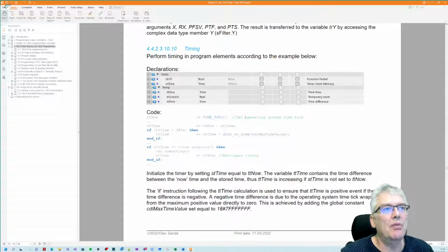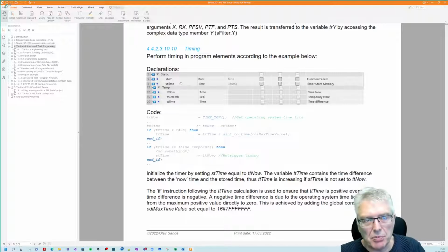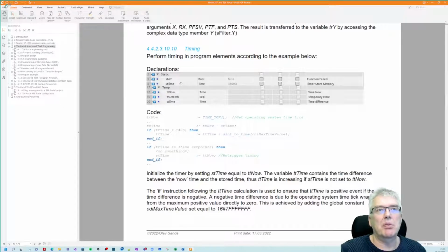So you have a static variable that you remember, because in a PLC your program is executing cyclically, and if you stay in a function block in a perpetual loop or something, your PLC is going to stop. You can't do anything because it's only your program working, your FB or instance. Nothing else is being processed in the CPU. You could put something on an interrupt, but that would interrupt this.